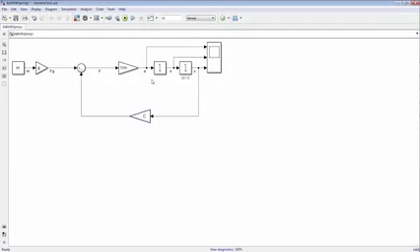So removing the minus sign in the gain block describing the spring constant, and in parallel changing the sign of the respective input port of the sum block, makes our model much easier to comprehend. And don't forget to really change the sign on the c again, because otherwise you have two times minus, which makes plus, and this is a completely different model.